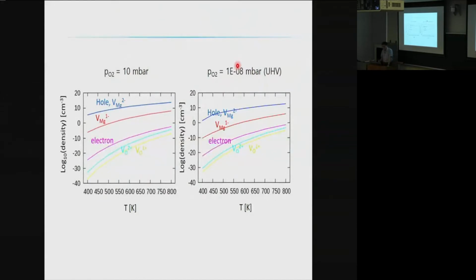So this was a little bit more oxidizing condition. Therefore your hole concentration has just decreased a little bit. So you can understand that by reducing the oxygen partial pressure, you are decreasing the hole carrier. Which is quite reasonable, and you can see that also from the data in the numerical calculations.